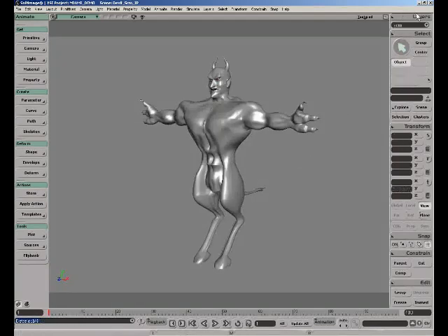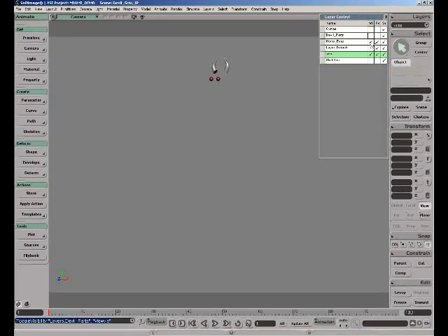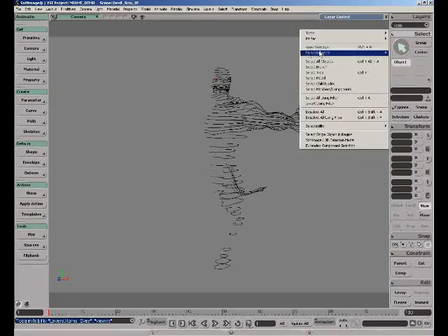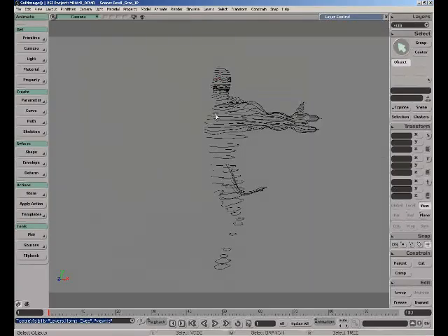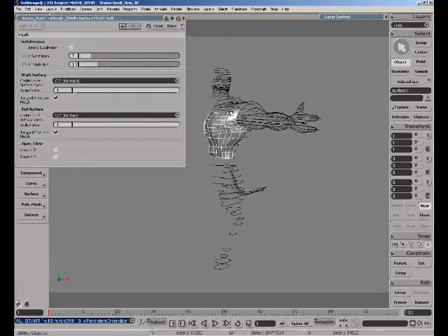And if we take a look real quickly at how we modeled those, we'll go and turn off this here and maybe turn on the curves. And just go here and show selection filters. We'll use the freeform tool just to show you how we made these individual components. We'll select a curve, want to create a new surface, loft, like so, right click, and there you go. So that's how you basically create these panels, and of course you can adjust the subdivisions.